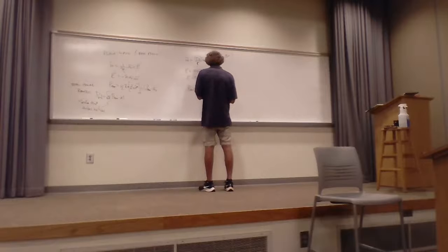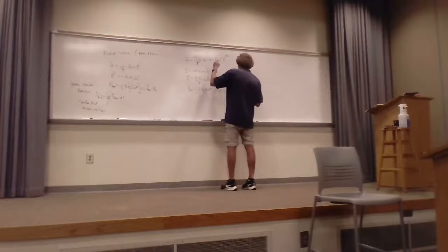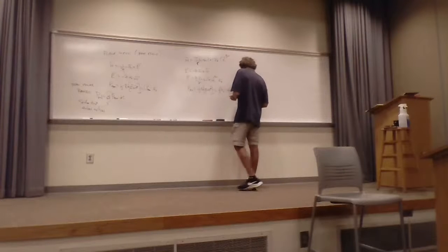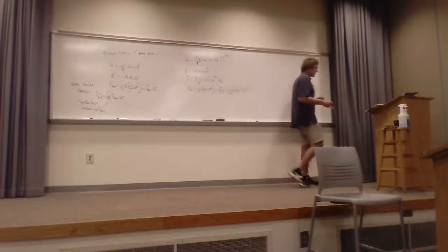So I'm just going to say it's going to be 1/2 times eta. That would be the atmosphere's eta naught, probably. In fact, I want to put it as eta naught. 1/2 eta naught times this squared. So it'd be IS squared sine squared of theta over R squared. And the phase term goes away and would be in the AR direction. Put it small r. Now that would be the power density in watts per meter squared of the field that's propagating.